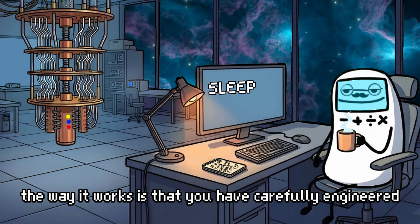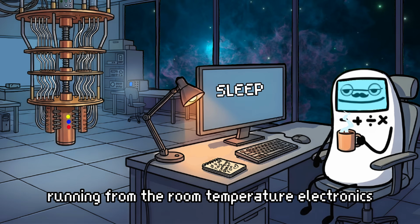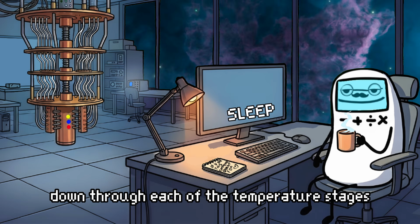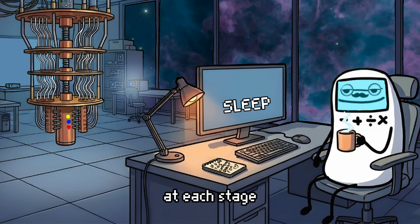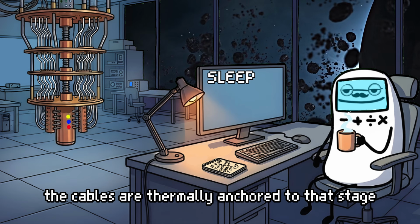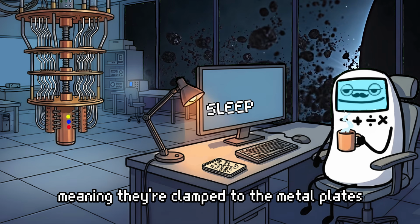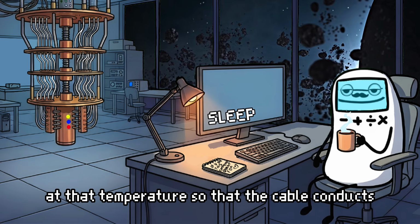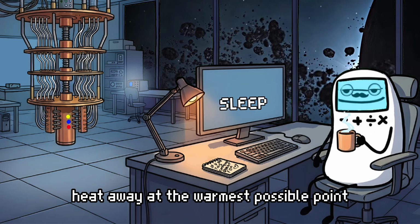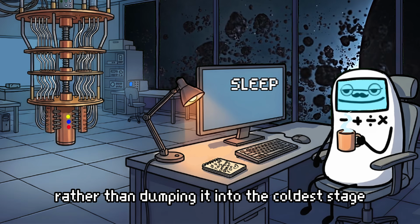The way it works is that you have carefully engineered coaxial cables running from the room temperature electronics down through each of the temperature stages. At each stage, the cables are thermally anchored to that stage, meaning they're clamped to the metal plates at that temperature so that the cable conducts heat away at the warmest possible point rather than dumping it into the coldest stage.